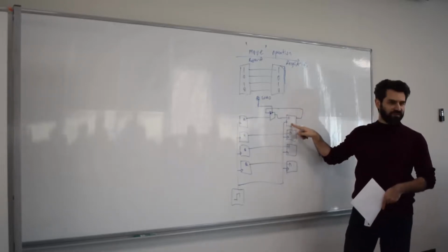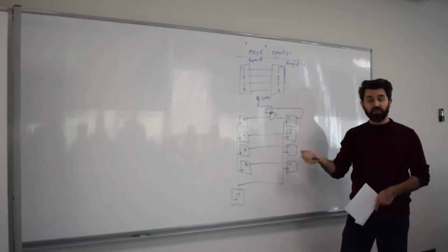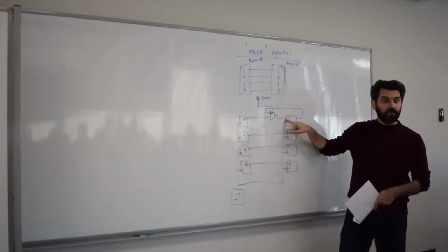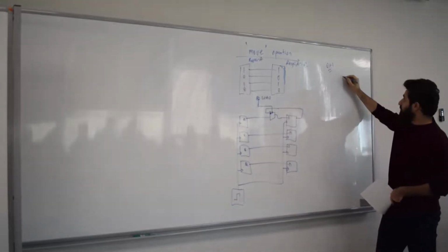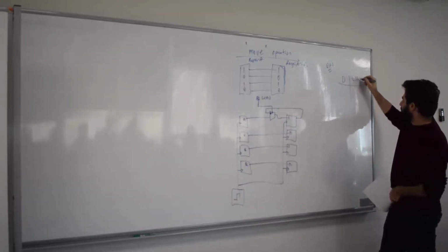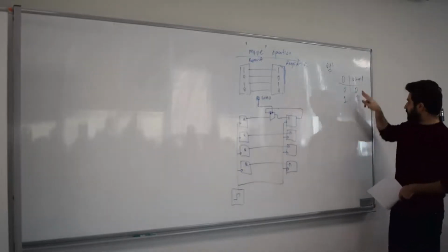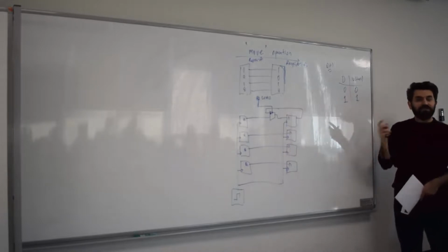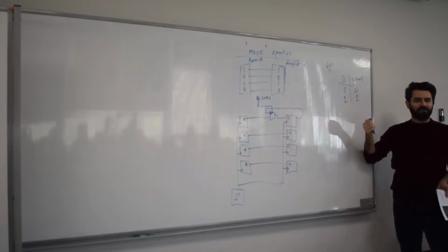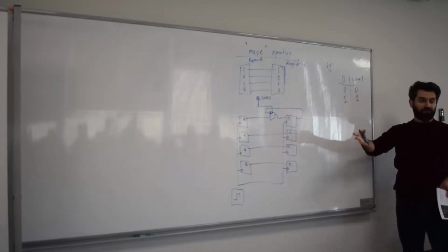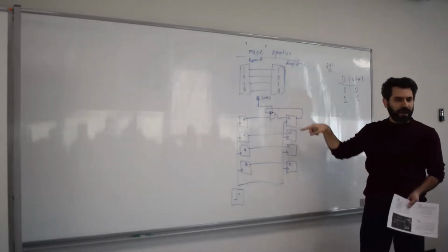So for example, if I'm storing 0, I'm going to store 0 in the next clock cycle. Because in a D flip-flop, remember, on each rising edge, the D flip-flop will look at its input and store that value. There is no QT in the truth table. Remember the truth table of the D flip-flop? QT plus 1: if D is 0, QT plus 1 is 0. If D is 1, QT plus 1 is 1. There is no QT in the truth table. So it cannot really store what it was storing by just playing with the input. The input is your next state, or whatever you're storing. Therefore, we need this kind of feedback.